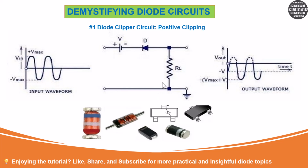The diode positive clipping is mostly applied in the area of noise reduction, basically in signal processing, and also in protecting sensitive circuit components from voltage spikes. You may employ these voltage clippers where you can set a reference voltage so that any spikes that may come through might not go above the certain threshold that you can set, so it will fall flat, as you can see here.